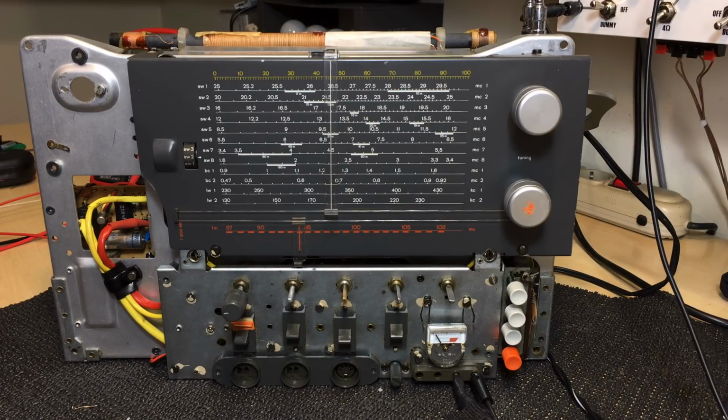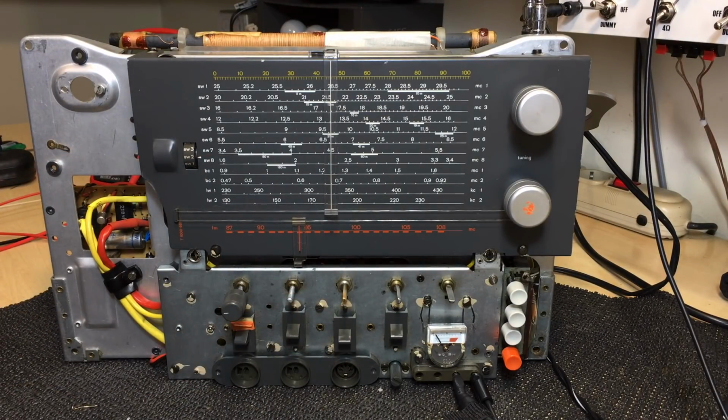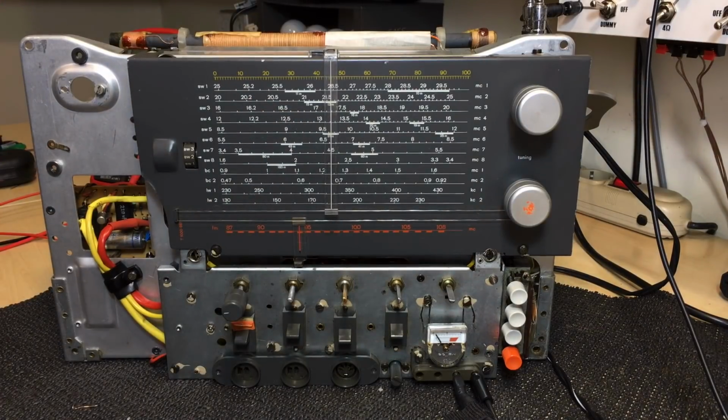But for now, we've got the BFO working, which was completely dead, and we've got the IF alignment, and this thing is very responsive when it's not giving us contact problems over there. It's working a hell of a lot better. Much, much better. And the FM is fantastic anyway. But for now, I'm going to work on that barrel connector. I've got to sort that out, and I would appreciate your help. If you can just advise me, how do you tighten those things without taking them out and risking breaking them? Because that would be terrible.